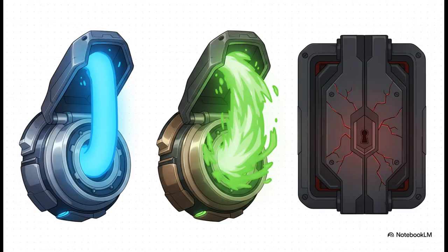So the crucial point is exactly how we utilize these regions. When it's biased into the active region, the BJT acts like a beautifully smooth valve. It becomes an amplifier, where the output is strictly controlled by the input. But what happens if we push it to the extremes? In the saturation region, it becomes a fully on switch, maxing out the current entirely. And in the cutoff region, with both junctions reverse biased, it acts like a fully off switch, blocking the current completely. This amazing dual nature, smoothly amplifying a signal or snapping completely on and off like a digital switch, is the absolute bedrock of modern electronics.